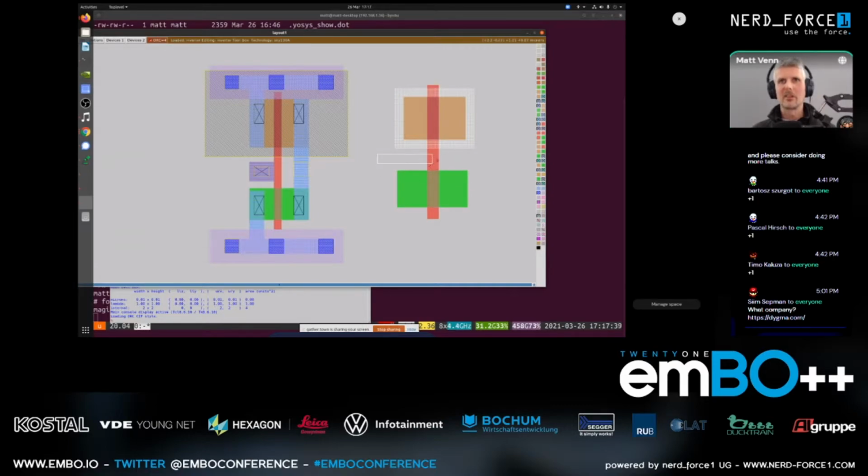If I do something like this, and then connect this one to ground and this one to plus, join those together with another one, and this becomes my output. I can make an inverter like this. Now you see this white highlight round here. Magic's telling me I've got 4 DRC rule violations here. As I've drawn, I've broken the rules from the foundry, and they wouldn't be able to make something like this. So when you're designing, you need to make sure your work fits within what is manufacturable. And a program like Magic loads the rules from the process design kit and shows you interactively.